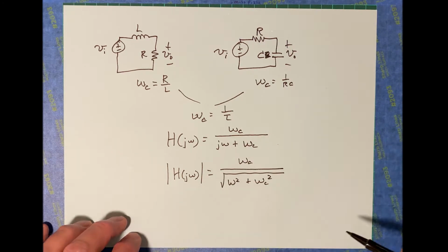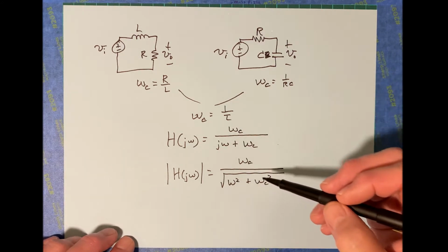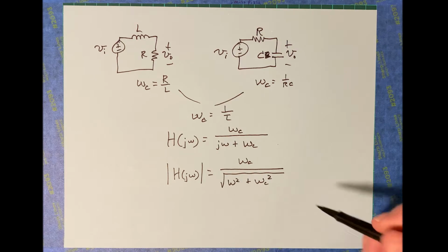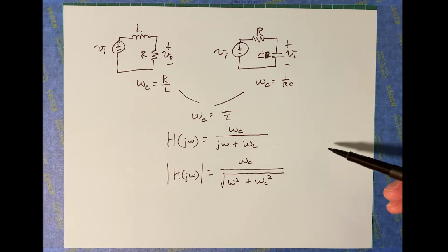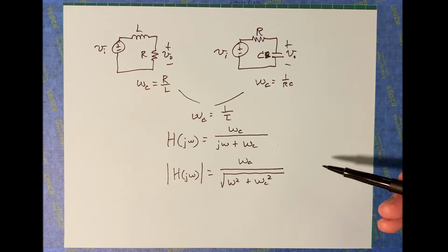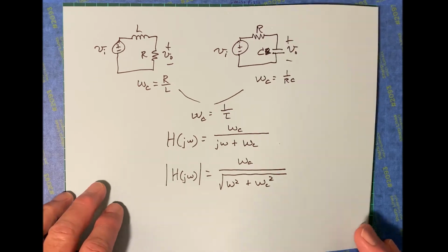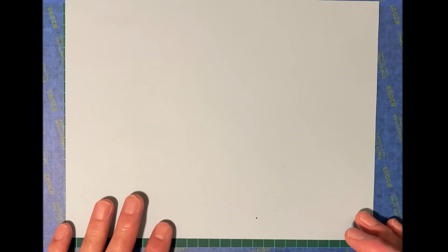So you've seen this now, and you can use this information to build a low-pass filter if you want to. It shouldn't be too hard from this point going forward. All right, build it and then create a graph. You know, we showed a little chart here, but you could do that in Excel and create a whole series of numbers and then plot those numbers if you wanted to, where you're stepping through various frequencies to see what the response is. In other words, you're building your own frequency response curve in that way. Or you could do it in MATLAB or any other type of graphing program like MathCAD. You could probably even figure out a way to do it on Wolfram Alpha if you wanted to.